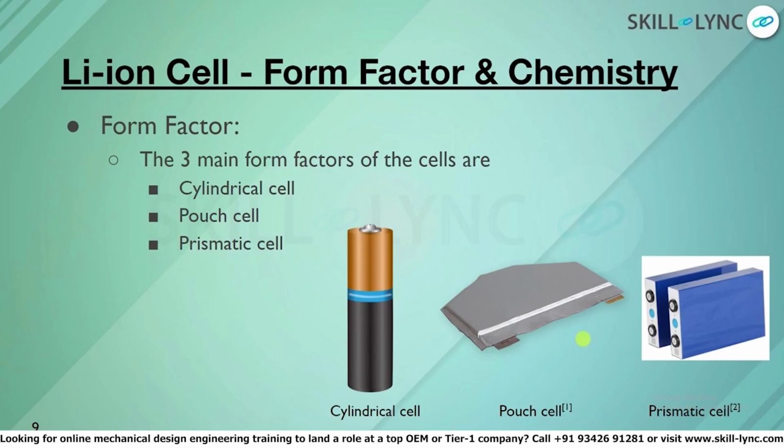So when we say a cylindrical cell, basically the cylindrical cell has been commonized throughout the world right now, so much that throughout the world only some formats are being used, like 18650, we have 2170, 3270. So when we say 18650, that is related to a cylindrical cell, and in 18650, the first two digits, which is 18, resemble the diameter. And the 650 is the length or height of the cell. So that is the cylindrical cell dimensions when we represent it as 18650.